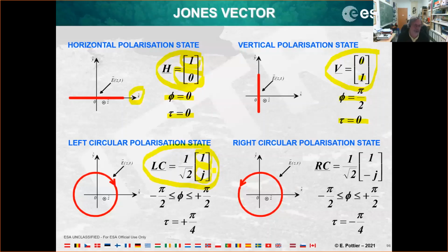Chi is a complex number. What does it mean? It means that in fact, I have a phase difference of 90 degrees between the horizontal components and the vertical components. So you imagine you take two sinusoidal waves, you make a shift of 90 degrees of the vertical compared to the horizontal, and the combination of these two waves is going to create a perfect circular polarization.